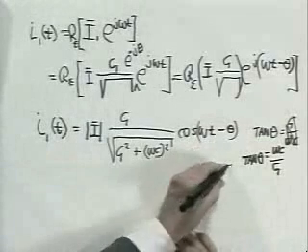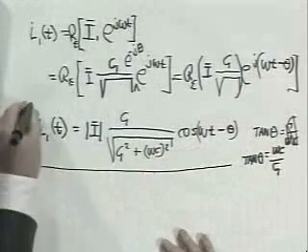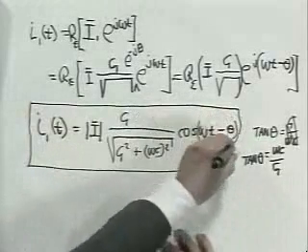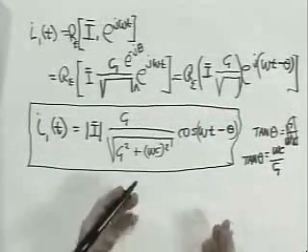So you're back to the real world. You've got a time function. And the important point is you got this time function without messing about with trigonometric identities. All you did was algebra, complex algebra, but that's no sweat. That enabled us to determine the current in one arm of this current divider. Along the way, we represented the complex admittance of that two-element parallel combination.